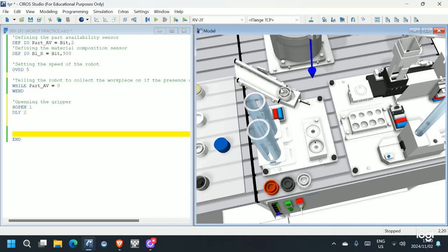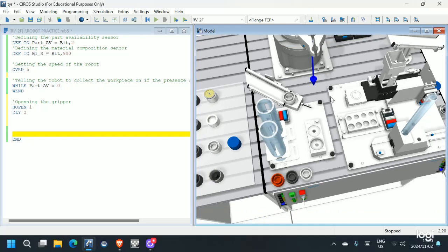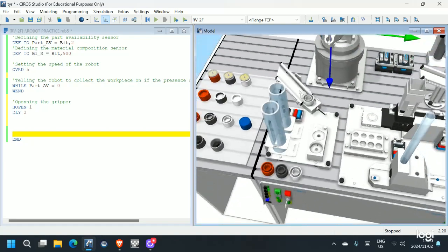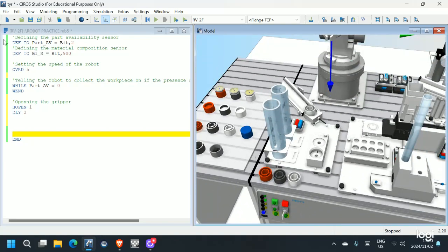Now we have to go there to grab the workpiece, right? As I explained in the previous video, between the different moves, we have MOV and MVS. I also explained what these moves do, and that's the importance of using them strategically. Since there are no obstacles here, we can just use an MOV to move straight and grab the workpiece.